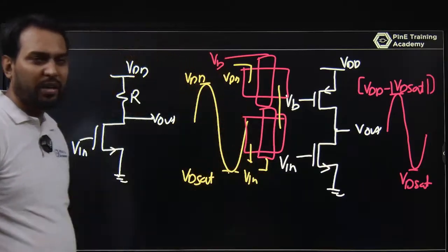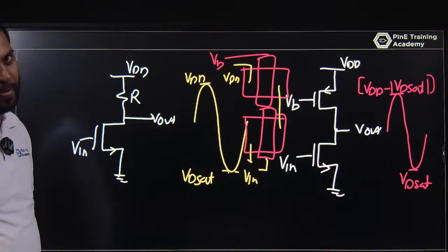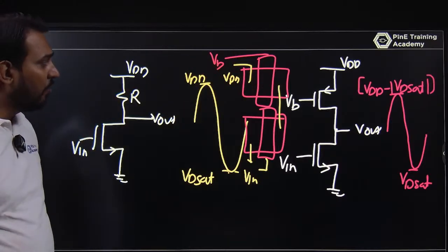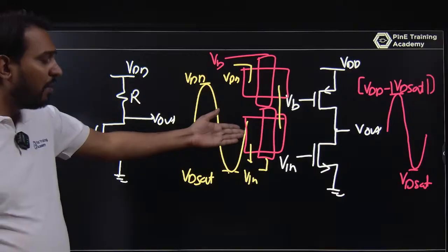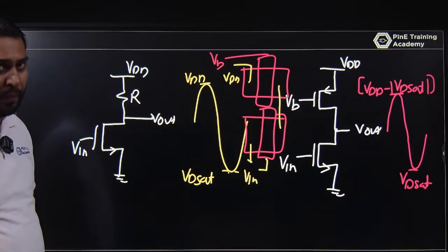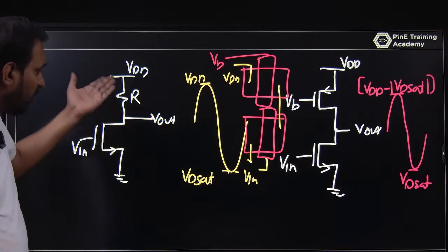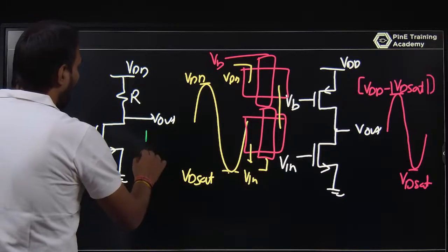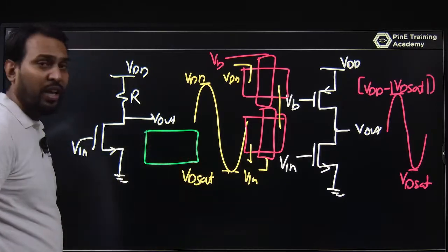The layout is completed here, and you can use a tap architecture. Of course, the body connection. For a PMOS you are using an N tap, for an NMOS you are using a P tap, and the latch-up problem was solved. But once you are going for this type of layout with resistance, it has a resistance with a poly.